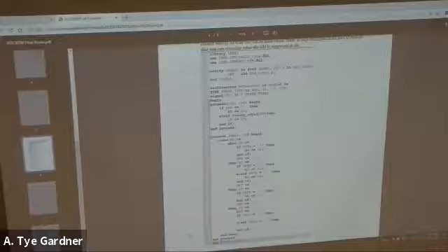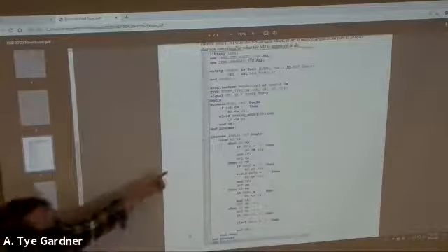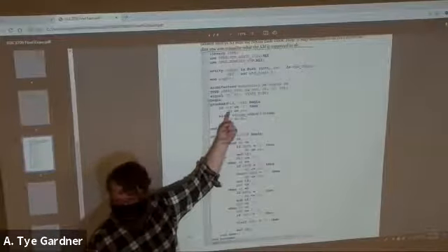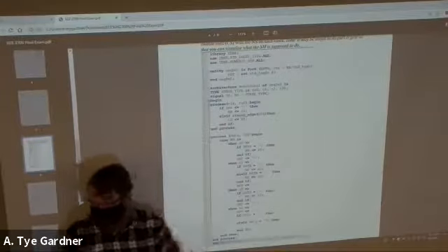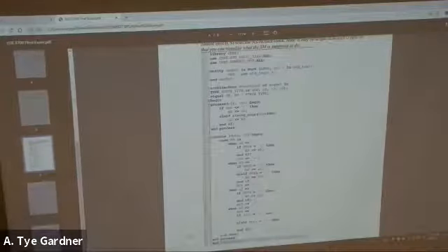There's another error in that process. To be current state for the next. Yes. Current state should go to S0, not next state. If I try and assign next state in multiple processes, I'm going to have a bad time. Okay, there we go. That's the general idea of that. I don't know if there might be another error in there, but we found 6, so I think we're satisfied.